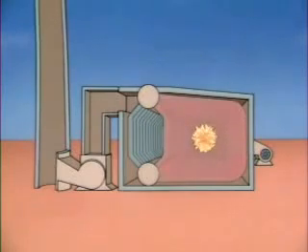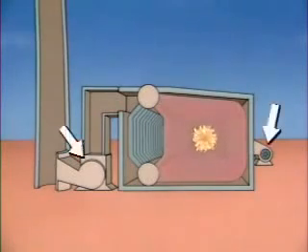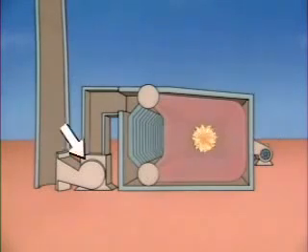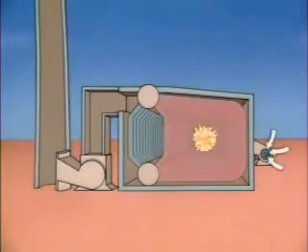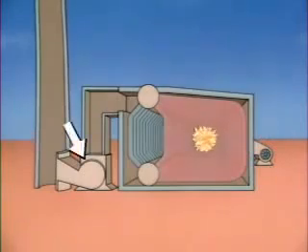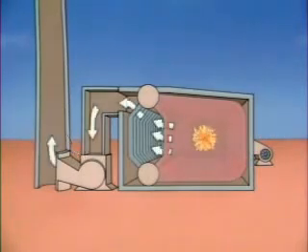The components typically used to provide draft are fans. There are two basic categories of draft fans: forced draft fans and induced draft fans. As their name implies, forced draft fans force air into the boiler. A forced draft fan draws air from outside the boiler and forces it through the burner into the combustion area. Induced draft fans create draft by drawing combustion gases from the boiler.